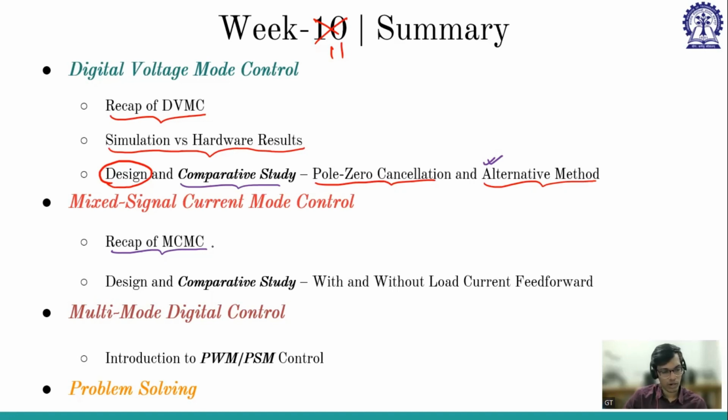So that's why we are going for peak current mode control. And similarly, we had discussed two design case studies, one with load current feed forward and one without load current feed forward.